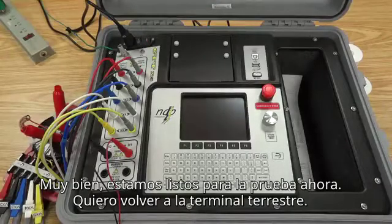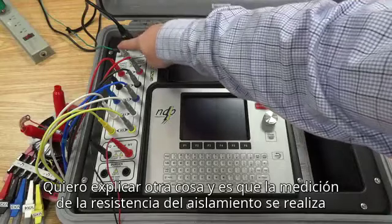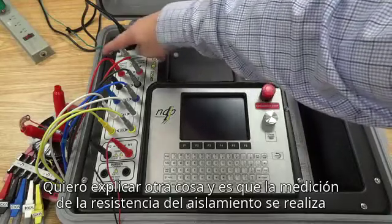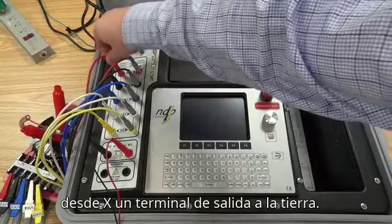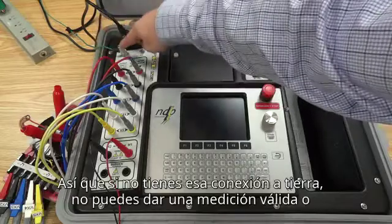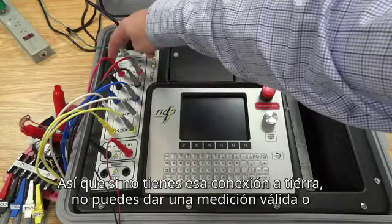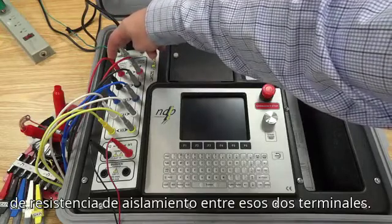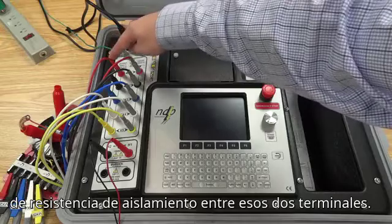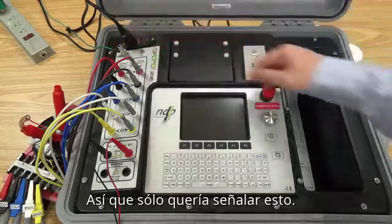Alright, so we're ready for testing. Now I want to go back to the ground terminal. I want to explain another thing, is that your insulation resistance measurement is performed from X1 output terminal to ground. So if you don't have that ground connection, I won't be able to give you a valid insulation resistance measurement. It checks between those two terminals. So I just wanted to point that out.